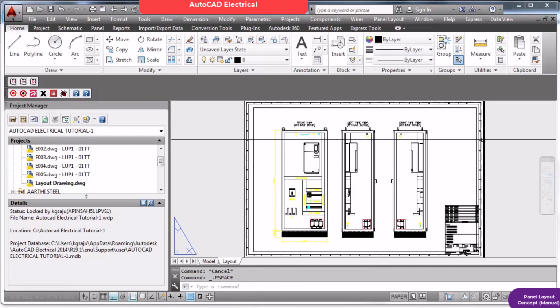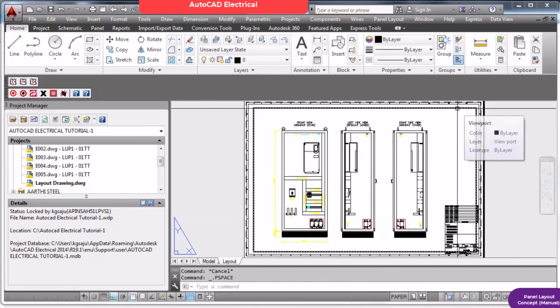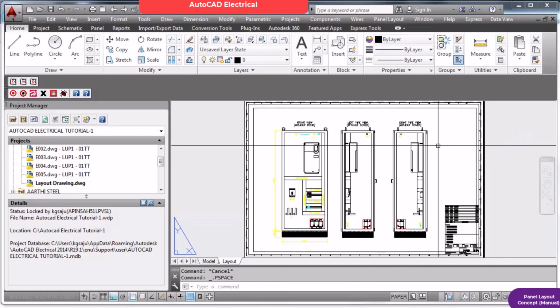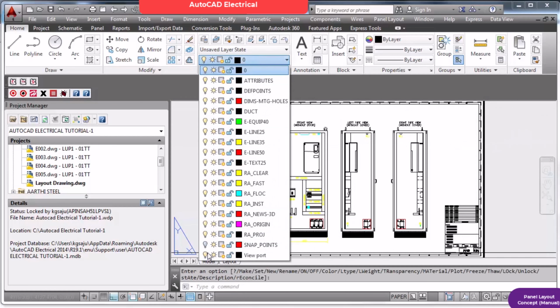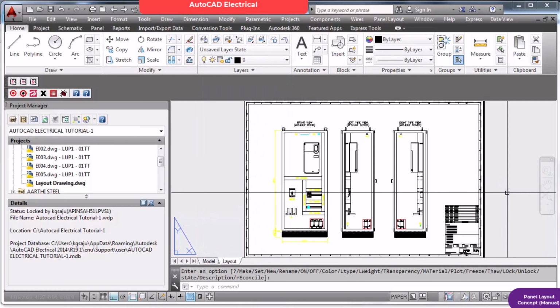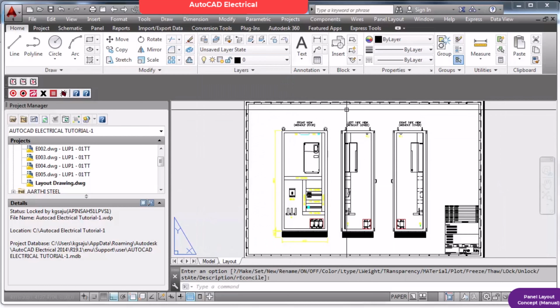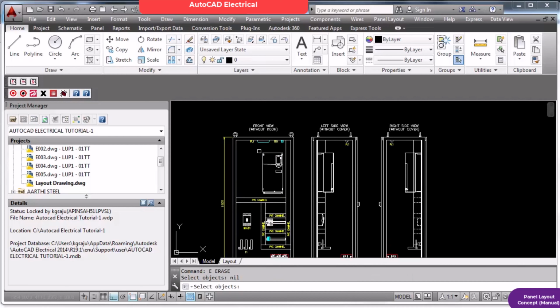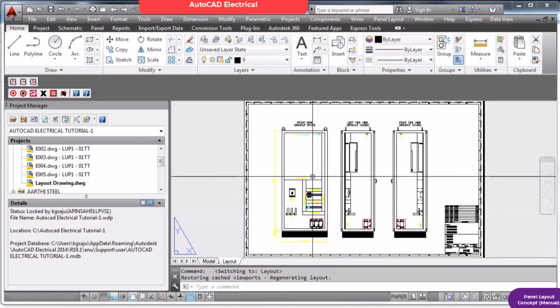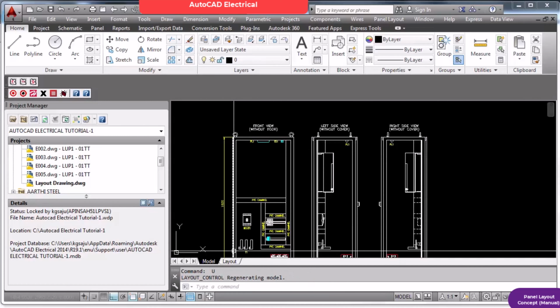Now your display has been locked. Now you go inside, you scroll here and here, you zoom extend, apply any command. You cannot move these objects from here and there. This is locked now. You cannot do anything inside this. That's the beauty. And coming out again, if you don't want this rectangle to appear in your drawing, go back here, hide the viewport layer. It is hidden now.